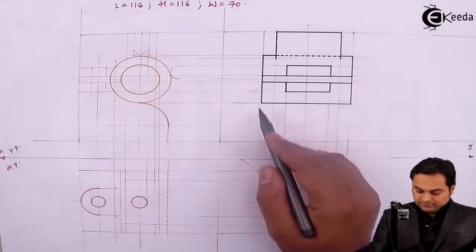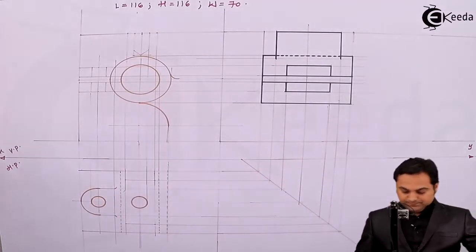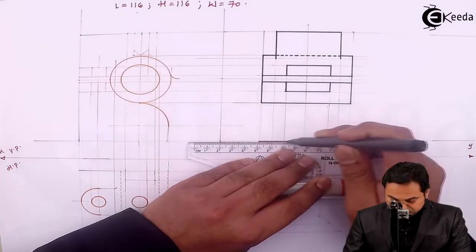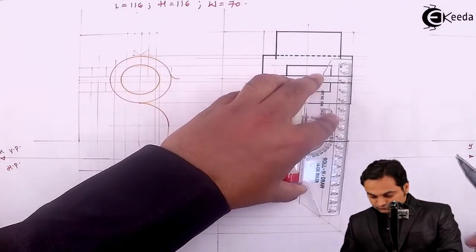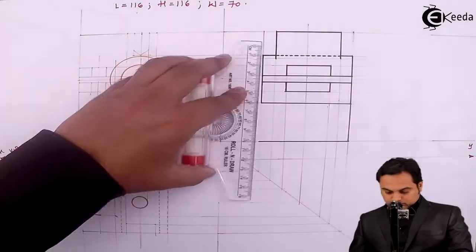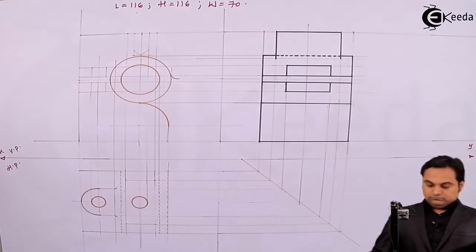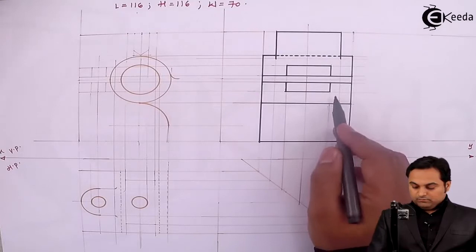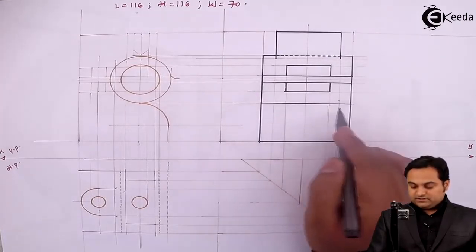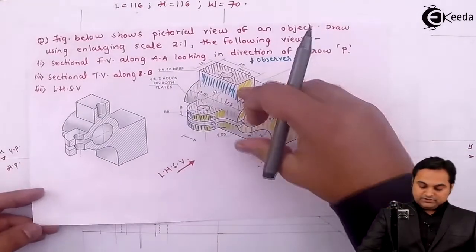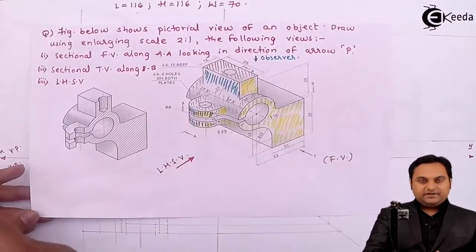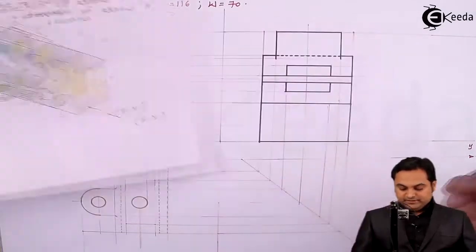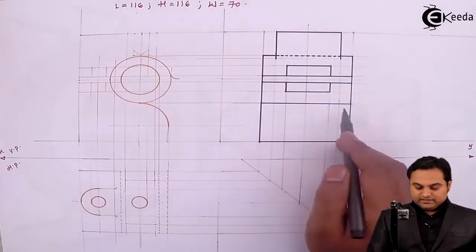So this complete surface will be visible as a rectangle of width which is there throughout. So there is a dark line between both these surfaces, because the cylindrical surface is extended, it is ahead, and the bottom rectangle is behind, so there is a change of plane and it is indicated with the help of a dark line.